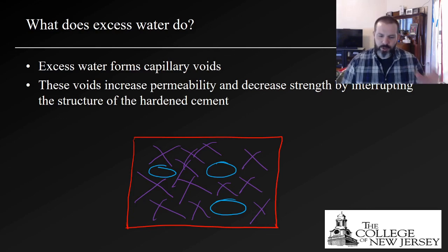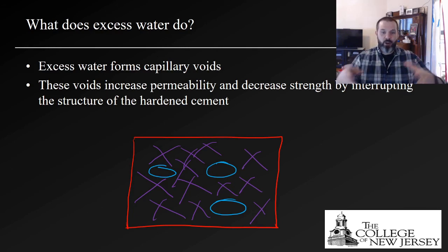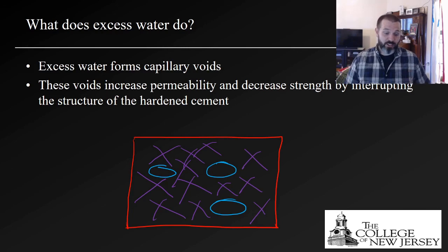So the real thing that's important in concrete is knowing how much water we're putting in the mix, because we want to be able to control our strength. Formal concrete design is basically filling a known volume with known materials and reducing the amount of water voids. So it's filling that volume and knowing how much water is actually in the volume.